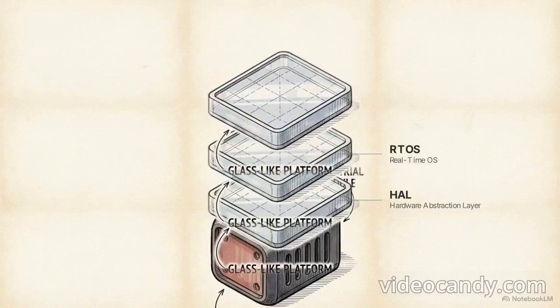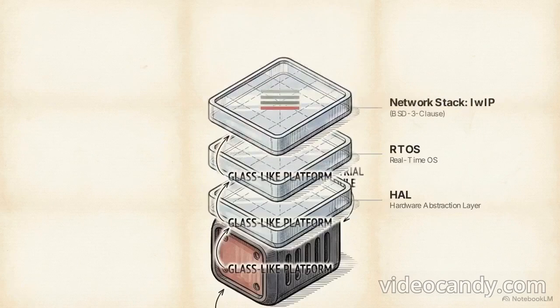Once the internal tasks are managed, the node must communicate its data to the broader industrial network. We find lwIP, or lightweight IP, listed in the declarations. This library provides a full TCP/IP stack specifically designed for microcontrollers with constrained memory limits.